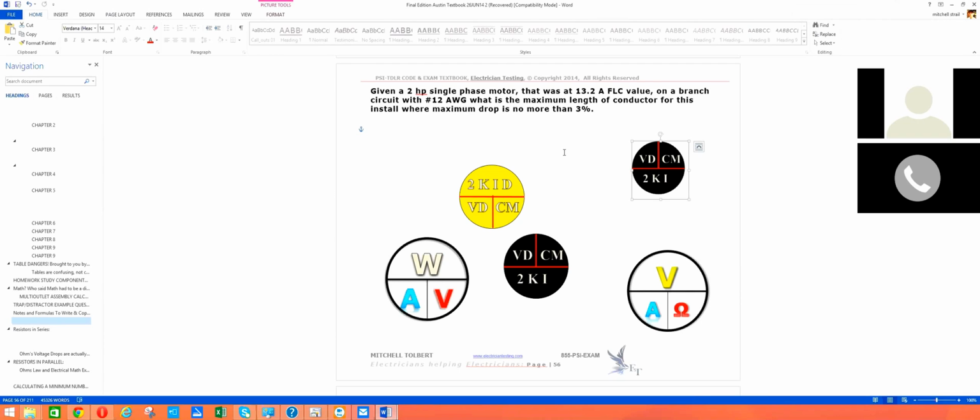I'm trying to see what the heck here. 430.250. Well, are you on page 350? You have just a regular code book, right? On page 350, do you see two tables? So is it 430.249? That's right. Put an X through that with your highlighter. That's the squirrel cage deal, right? The 430.249 might be an induction squirrel cage, but what the issue really is, is that it's a two-phase system. Oh yeah, I see what you're saying there.